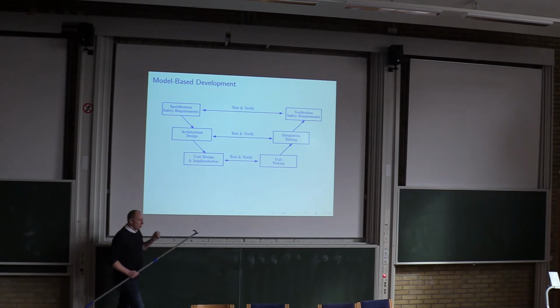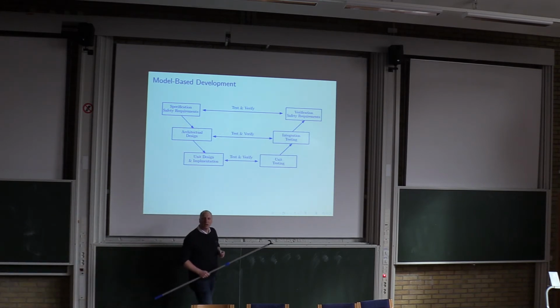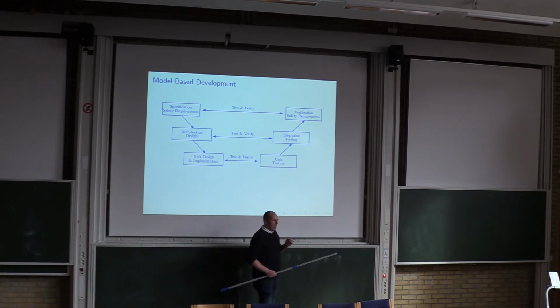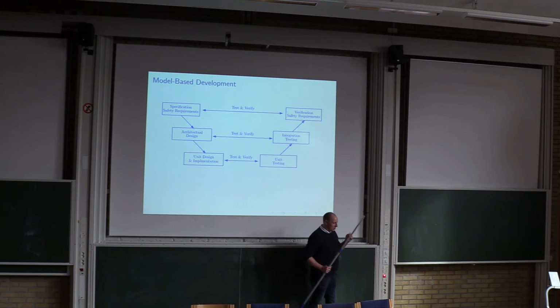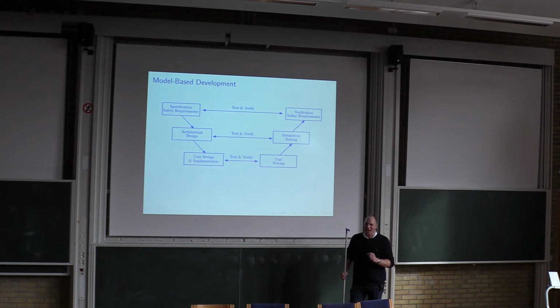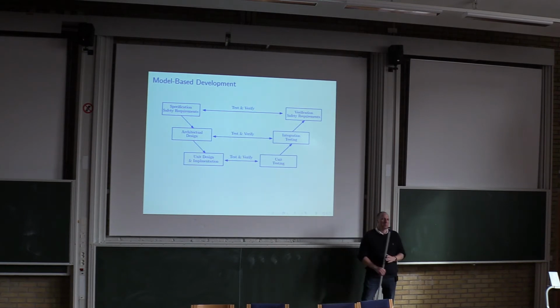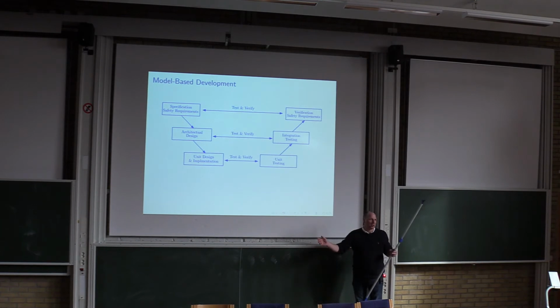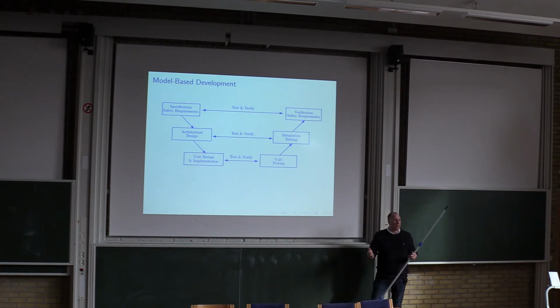So that is something you typically call model-in-the-loop testing. And you would like to do testing as much as possible on your models, because the models, they can scale. You can buy a huge cloud server, so you can have thousands of different processors running in parallel. So there you can really test a lot of things.